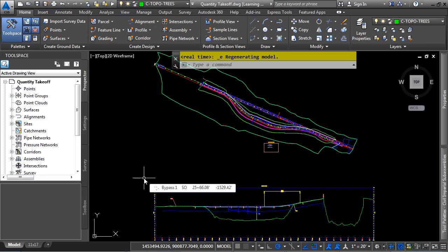Pay items can be associated to AutoCAD lines, open or closed polylines, blocks, or any AutoCAD or Civil 3D object after they have been created. When pay items are assigned to AutoCAD Civil 3D code set styles, a corridor object is automatically assigned those specified pay items. As well as any Civil 3D pipe network parts list that you associate pay items to, those pipes and structures will automatically be tagged as well.